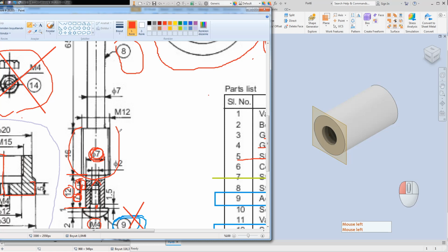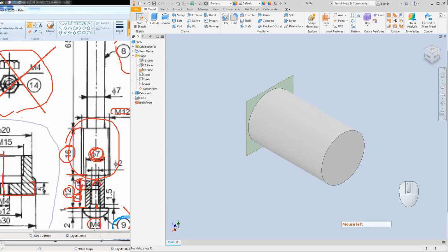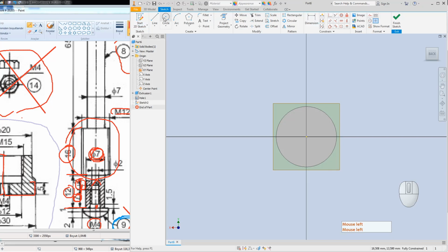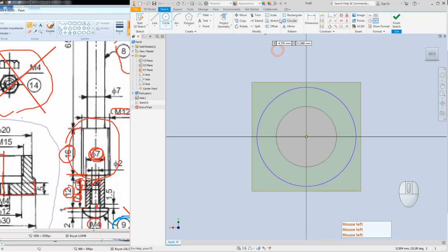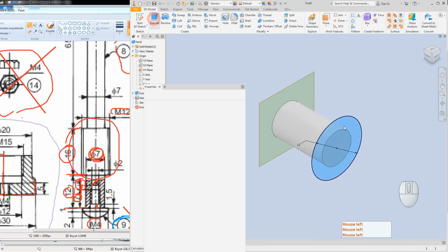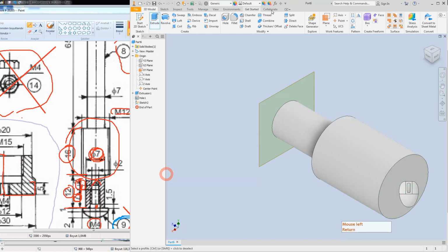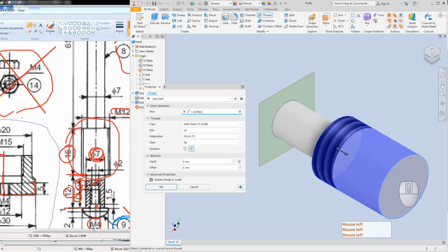The next part, I will just make a 12mm with 16mm length cylindrical part. I will add at the back side of this, start new. It is 12 and make 16 millimeter in length to the other side. Also, the new thread, which is metric 12, whole length.